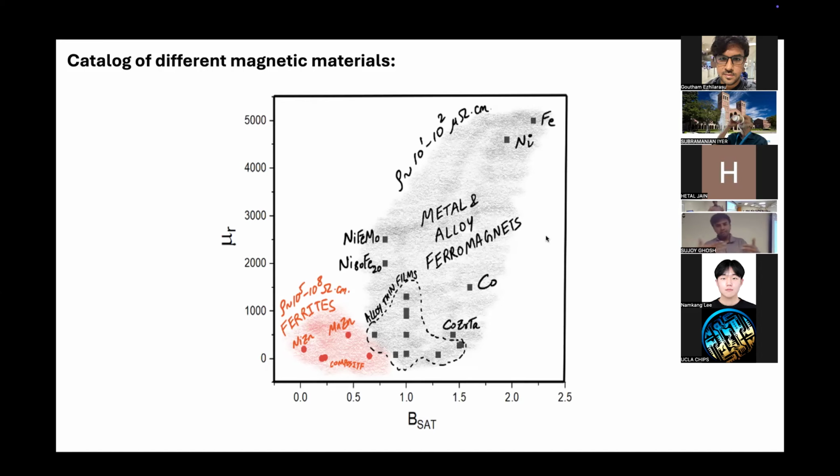There's also another kind of opposing factors, which is the inductance density and the quality factor. Generally, when you make an inductor that has a higher density, it tends to have a lower quality factor and vice versa, right? That's why air core inductors have very high quality factor. You can even get 100, but they have very low inductance density. But if you take a magnetic core inductor, it can have very high inductance density, sometimes even 1,000 nanohenries per square millimeter, but then its quality factor would be like 5 or something like that, right? Because there's again an inverse relation between the loss as well as the inductance density.